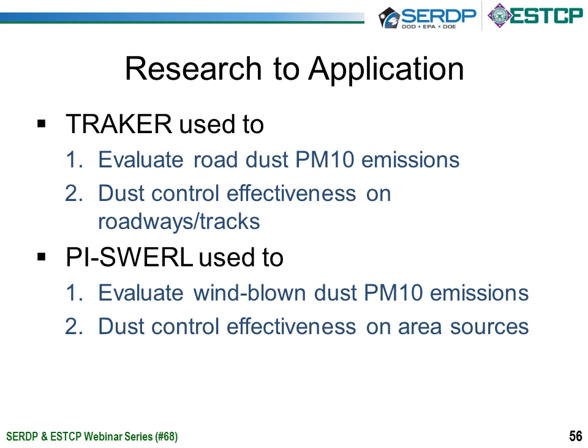So the PI-SWERL has been used to evaluate wind-blown dust PM10 emissions, and that's a very effective thing. It's being used by the California State Parks here at Oceano at the moment. And we can also use it to evaluate dust control effectiveness on area sources that have been treated potentially with mitigation efforts, and look at how well that's holding up over time, how fast it's degrading, and allow managers to determine if they've got a cost-effective product applied.